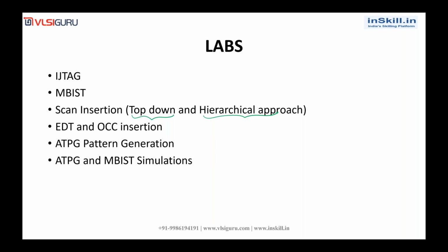For simulations, we will be covering only no-timing simulations. Why? Because in order to do timing simulations, one input file is required, called the SDF file, standard delay format. In our labs, we do not have the SDF file. That is why we will not be covering timing simulations. We will be covering the practicals of only no-timing simulations.